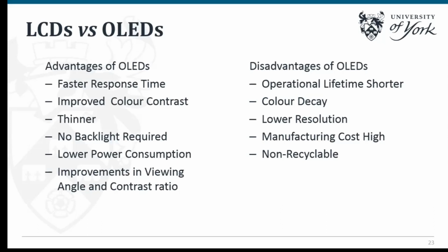The first is that operational lifetime is shorter, and that is simply because organic molecules are not as stable as inorganic molecules when you're cycling between two different energy states, particularly in blue OLEDs. That's a very high energy transition, so you can very quickly burn out your molecule, so it will no longer absorb and emit light.